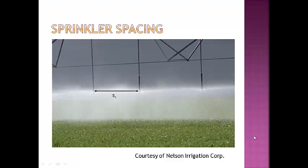Okay, let's move on. We'll use that in just a little bit, but for right now we need to discuss some of the basics of pipe hydraulics. And so we'll first look at sprinkler spacing. Sprinklers are spaced along the pivot at varying distances. Usually they're closer together the farther out you get. These are the drop tube sprayers that are used in Arizona. To avoid evaporation, rather than having large sprinklers on top, they have closely spaced sprayers down low, so the water doesn't have so far to travel to get to the ground.